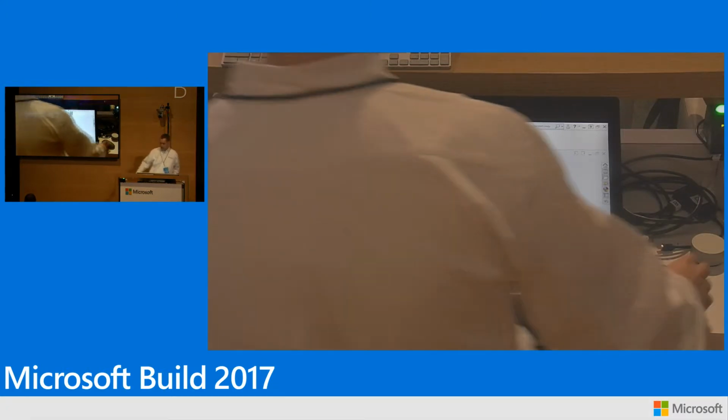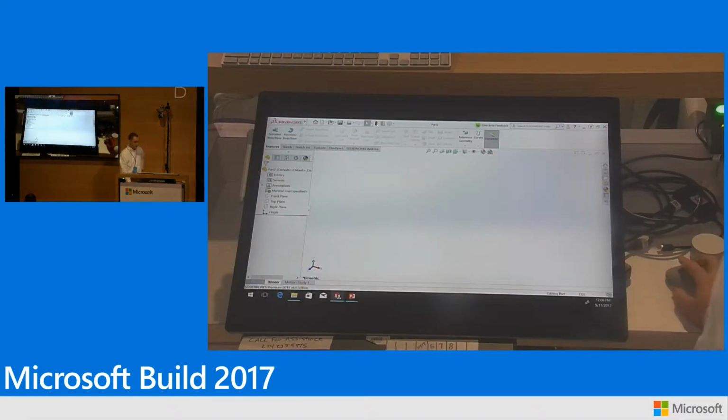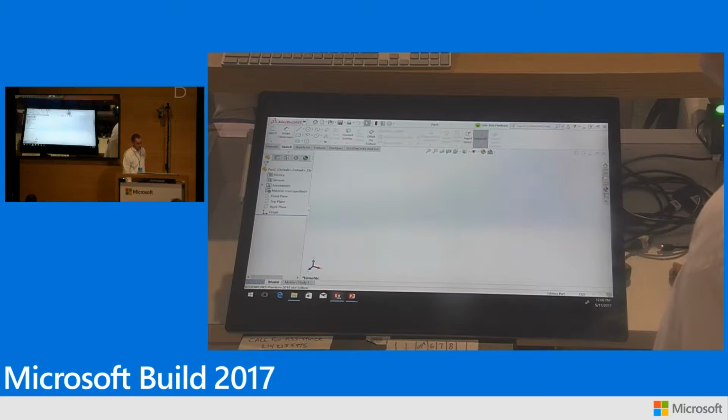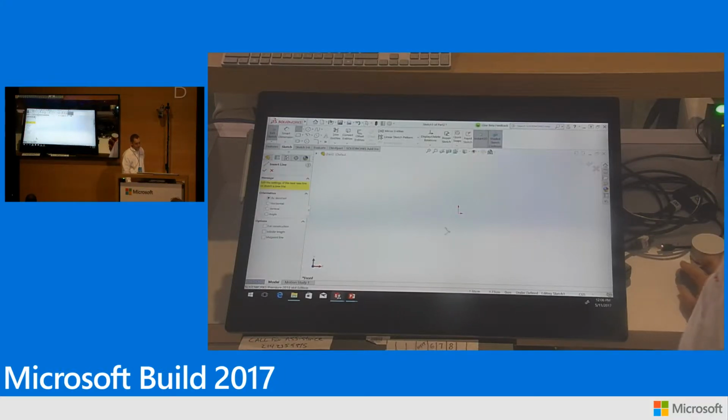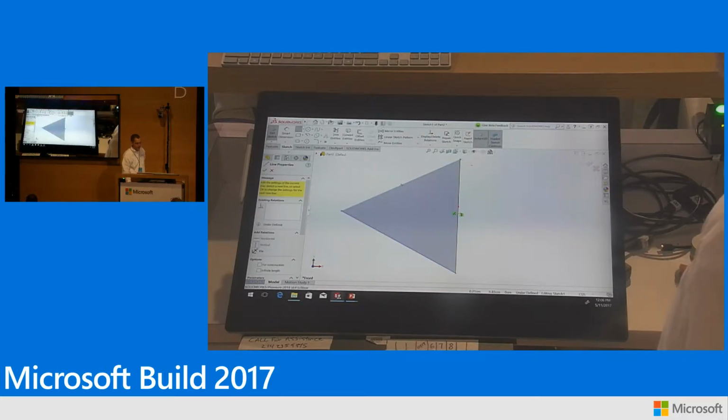So if you're going to do this here, you'd start a sketch on a plane and start picking tools and dropping the lines that you want to draw. And you start to get shapes, and we fill in the contours for you. So you'd pick tools like circle, draw those in here.